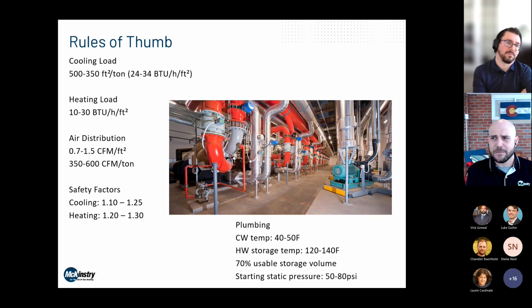And on the heating side, heating loads can be as low as maybe 10 BTUs per hour per square foot. I've seen that kind of load in Massachusetts in a building that was very, very well constructed, very well insulated, with a very tight envelope, and 10 BTUs per square foot is also maybe on par for Tampa, if you have code minimum levels of insulation and that sort of thing, in new construction.